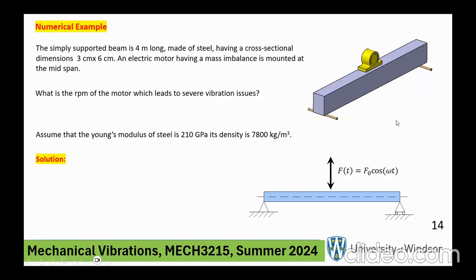Now, the information about the material properties of the beam is given here. Obviously, without that, you can't do the problem. So we know its density and we know its Young's modulus. Basically, we have a harmonic force acting on a mass. Loosely speaking, we pretend that the mass of the whole beam is the mass being represented in our model, and then there is a fancy spring here.